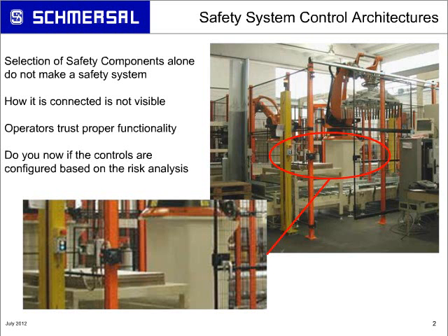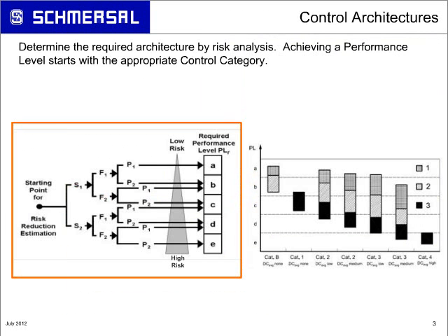In deciding those factors, you see the selection charts, such as those listed in ISO 13849, that select the performance level. When you look at severity of harm, frequency of exposure, and possibility of avoiding it for a particular safety function, whether it's an emergency stop function, a guard door interlock function, or various other safety functions in the machine, it's going to drive you to a specific performance level.